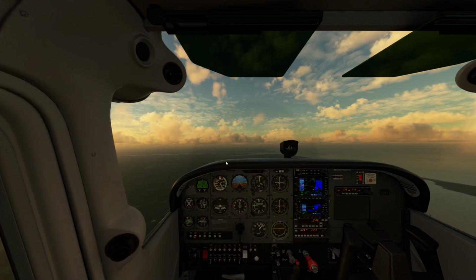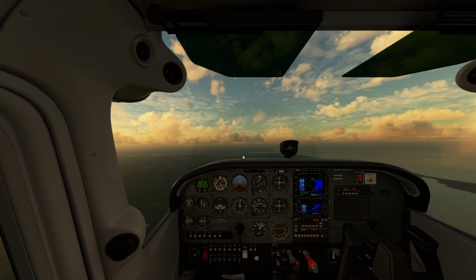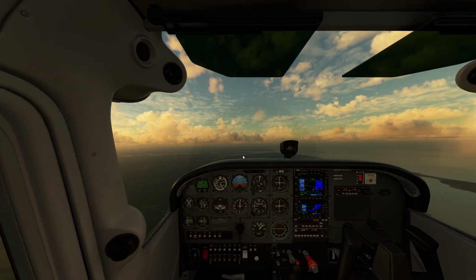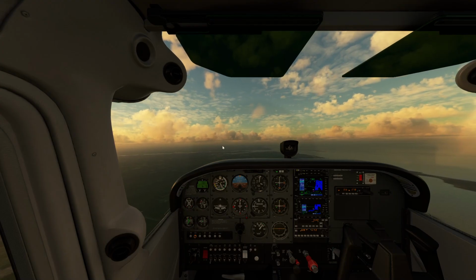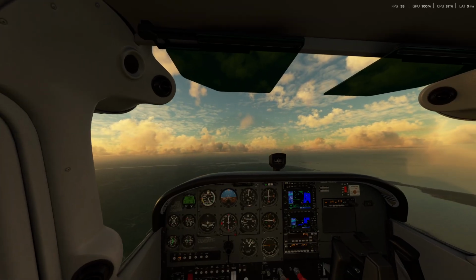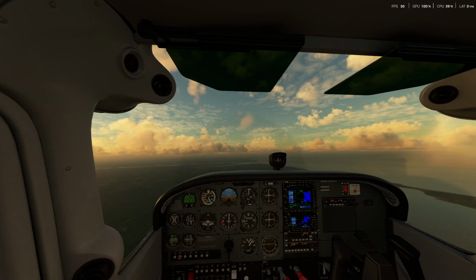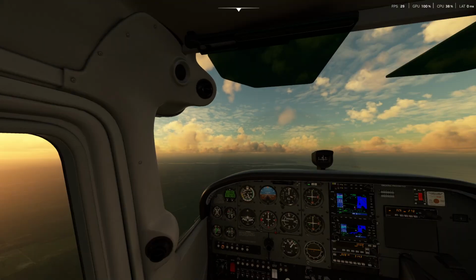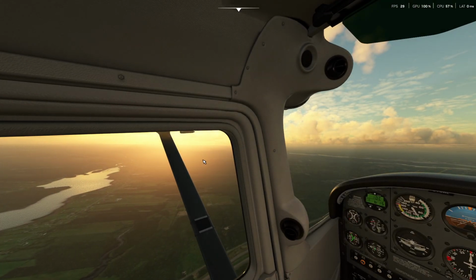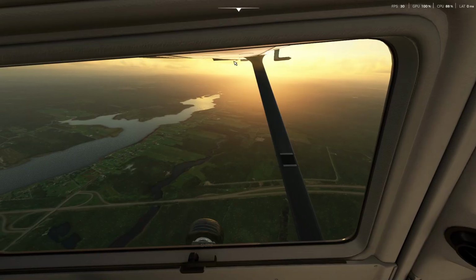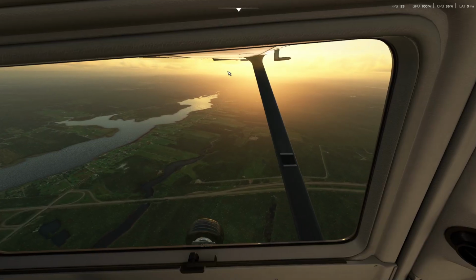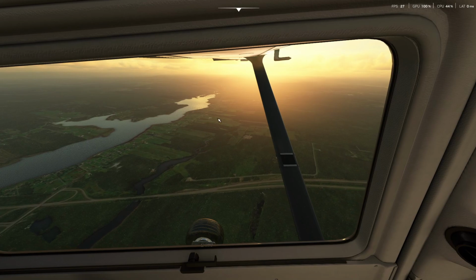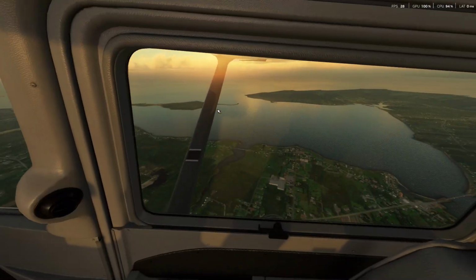So between basically here to here, it's about 1/3 ground that you would see in front of you, and about 2/3 sky. But yeah, it looks good. It's about a normal cruise attitude. And again, if you look out to your left, you can see where your wing is in relation to the horizon. It's pretty much parallel, left side and right side.